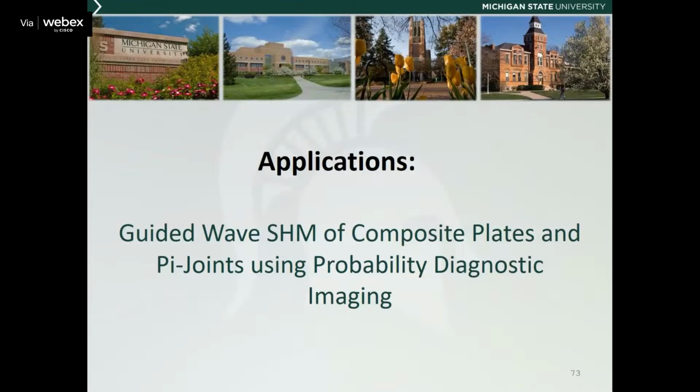So for composites, you can use guided wave SHM to monitor the wave propagation and reflection in these layered structures. Another interesting structure is a pi joint, where the shape of the structure is like a pi, and this is a very critical component in structures which bear the loadings.